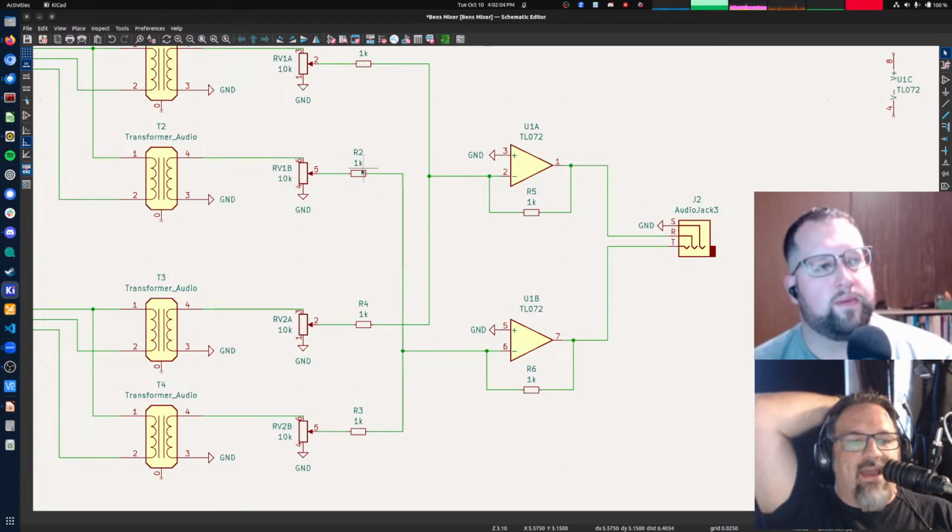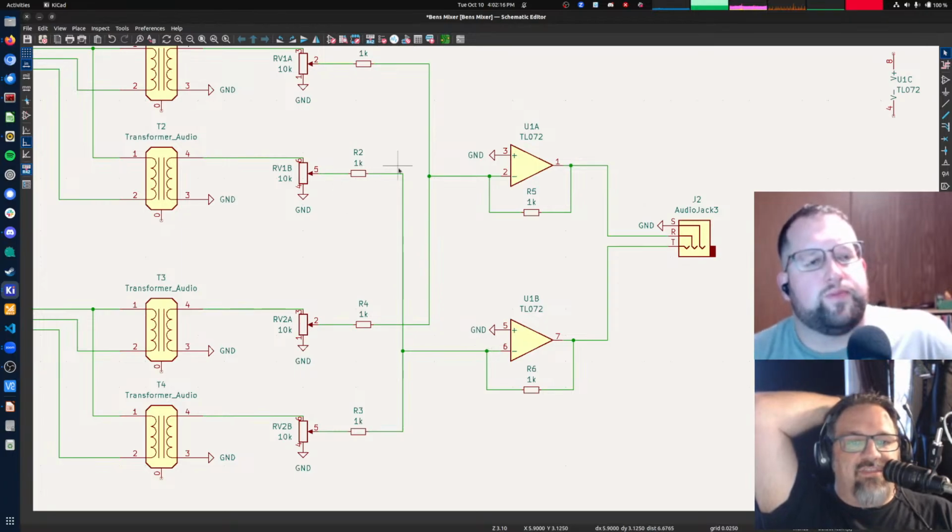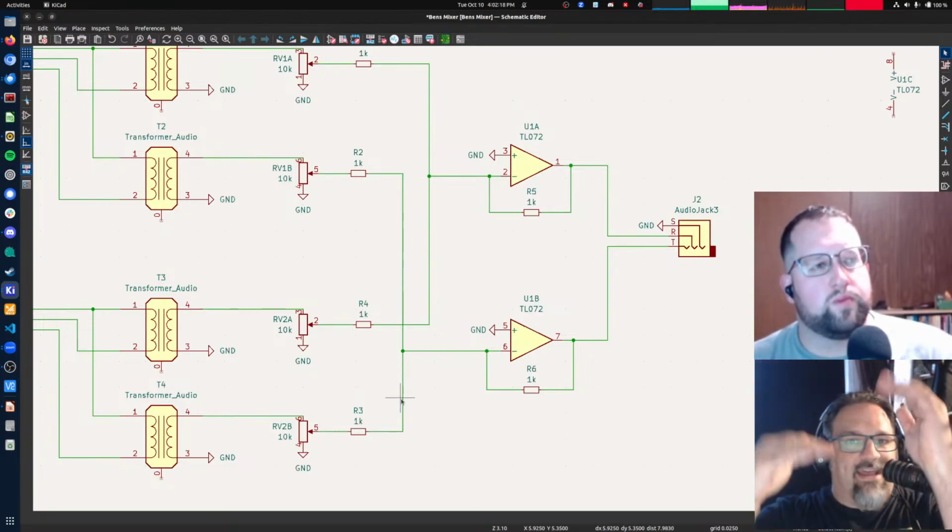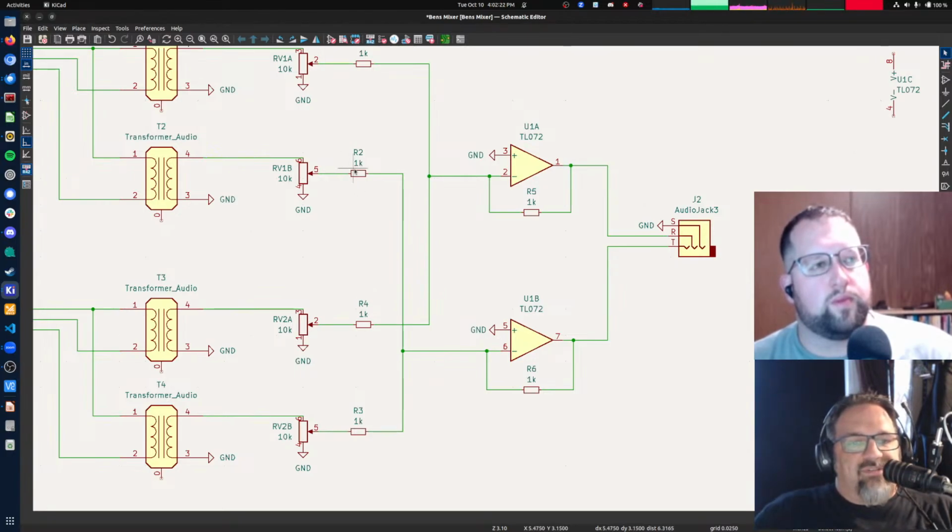there isn't a way for a signal coming in here to impact this, because the way that happened before, let's say you pretend this op amp isn't here and you've got nothing over here trying to control this. This node will just vary up and down as the signals change. But whatever current comes in through this resistor, this op amp will draw that same amount of current out through the output so that it doesn't have a place to go through here.